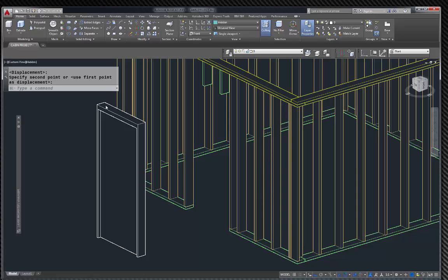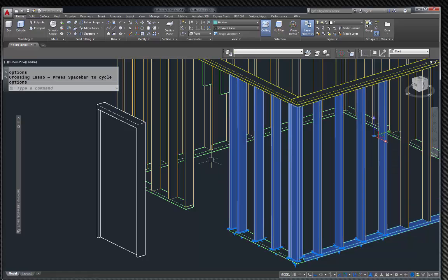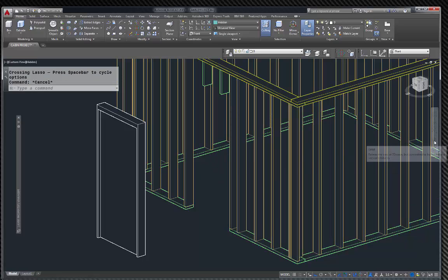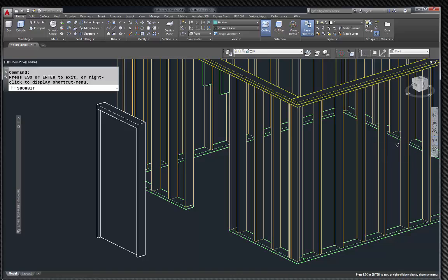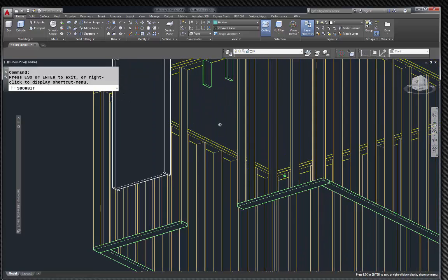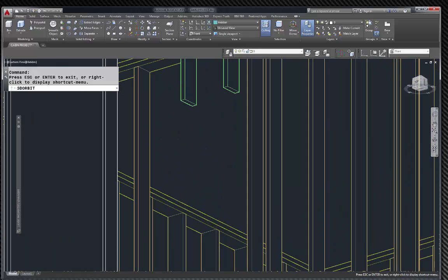And as a header here for a 3.0 door, I can get away with a 2x6 on edge, and we use 3 of them on edge. So I'm going to go in here, use my orbit. Come on, orbit. I'm going to move up these.